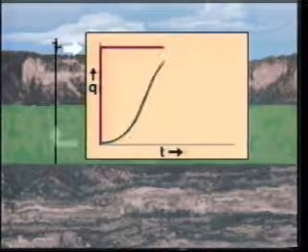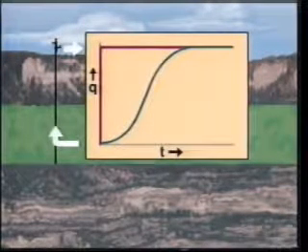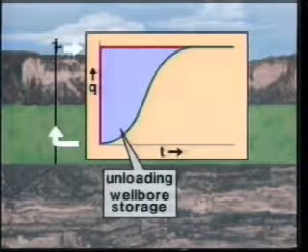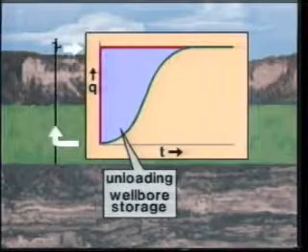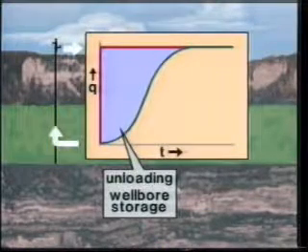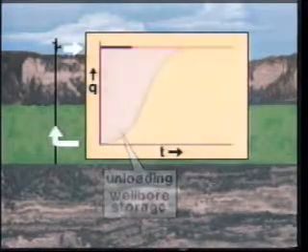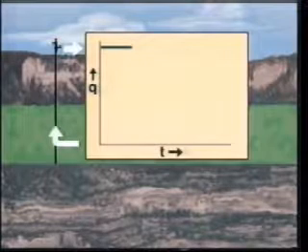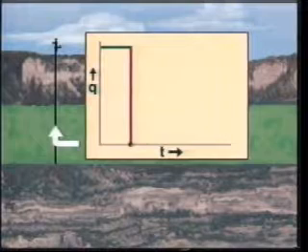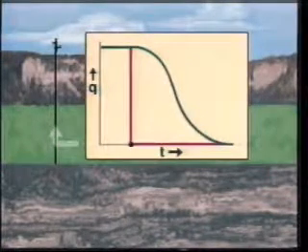Showing the 2 flow rates simultaneously, we see the magnitude of delay in flow response at the formation. The delay is caused by what we call unloading, a form of wellbore storage. The delay in flow at the formation is also reflected by a delay in any pressure change in the formation. If we produce the well for a period of time and then shut the well in, as we would for a build-up test, we see that wellbore storage is also present for a build-up test.